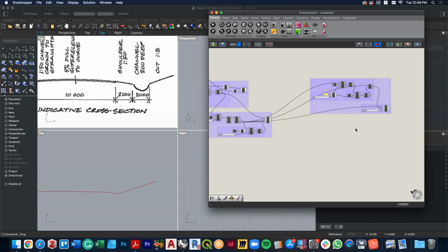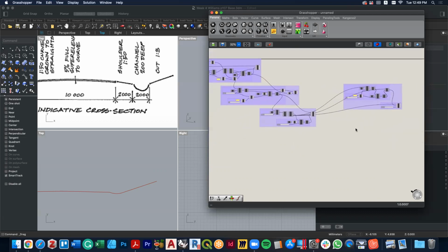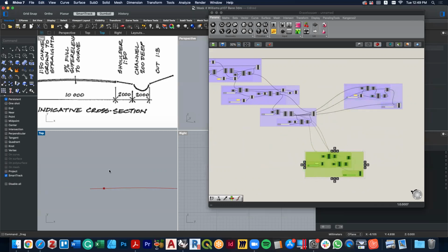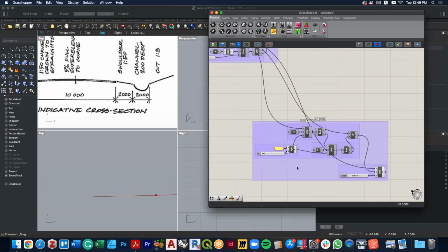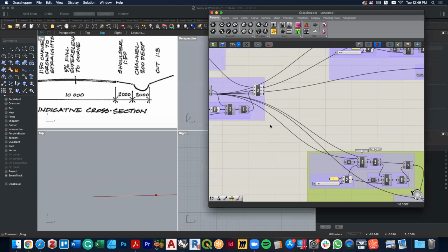Now I have to create a fill batter. And so this is where it's a bit of a mind flip to do this, but it's a similar process. So I'm going to go Control-C, Control-V. So now what I'm doing, if you can imagine, is I'm working on the other end there. Now, if we look at where our construction geometry is, we're going to have to start using some negatives in this process to get the same effect. So we're going to have to be a little bit careful here about how we unpack this.